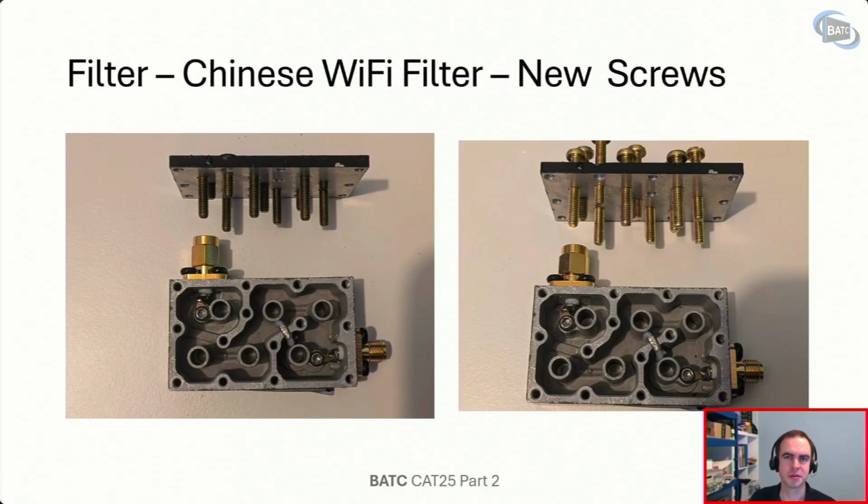And so one of the first steps that Tim had to do, and I had to copy him on this, was to replace those tuning screws. So I found some brass tuning screws rather than steel, and inserted those instead. And then with calipers, I very carefully measured the exact exposed lengths of all the threads and attempted to match that as a starting point for tuning.